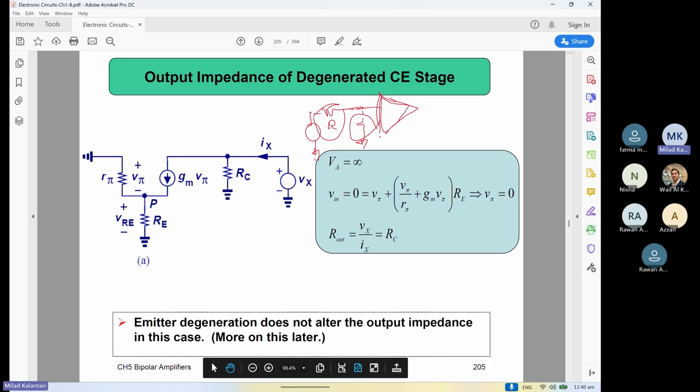It matters the power, but now we are just focusing on the voltage. Sometimes we like to increase the maximum power transfer, but now we are thinking about the voltage transfer. For power transfer, you need to adjust this resistance value to match the source value to get maximum power transfer. You remember there is a maximum power transfer theorem, right? But in this case, we are just caring about the voltage.